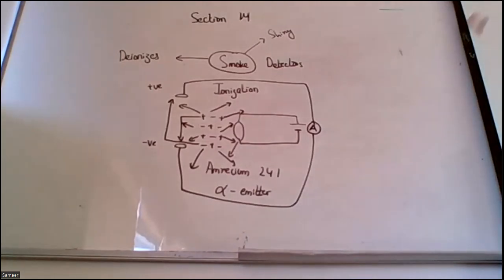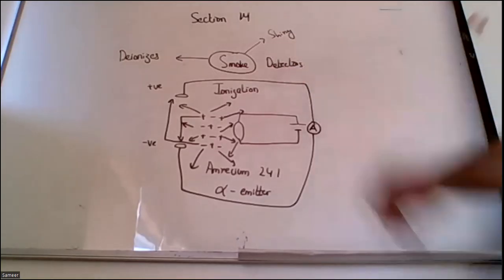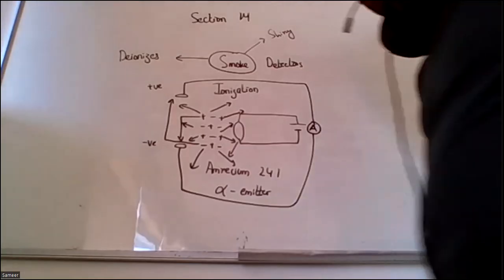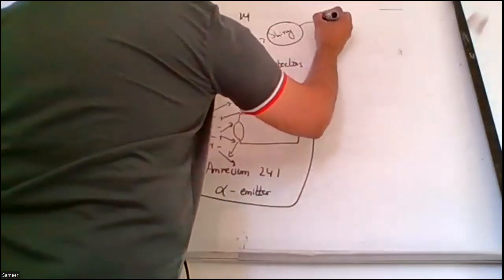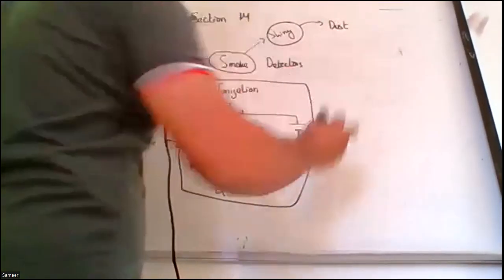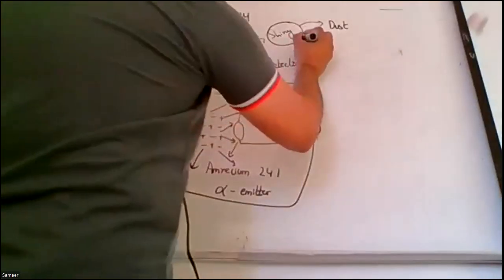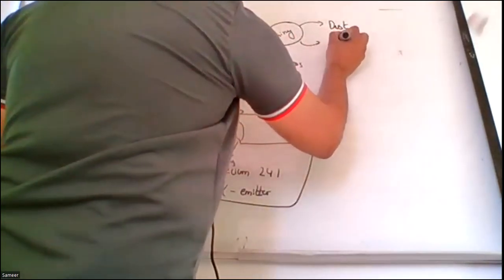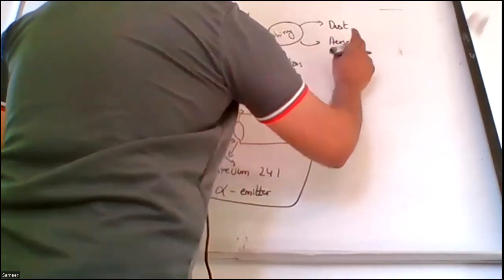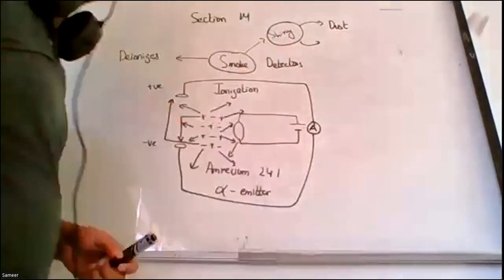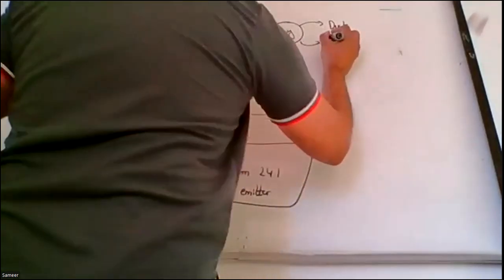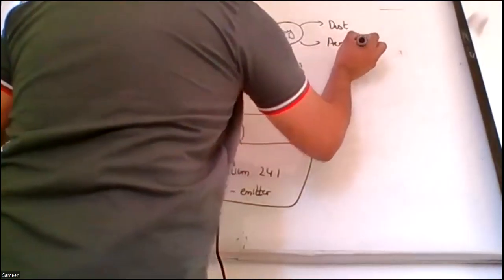In the photoelectric and the ionization detectors, the false alarm ratio is very high. Because when we say smoke has shiny particulates, it is not the only case. Shiny particulates are also associated with dust particles, and with any type of aerosol signatures. Any type of sprays, perfumes, mist or water, any aerosol signature, and the detector will operate.